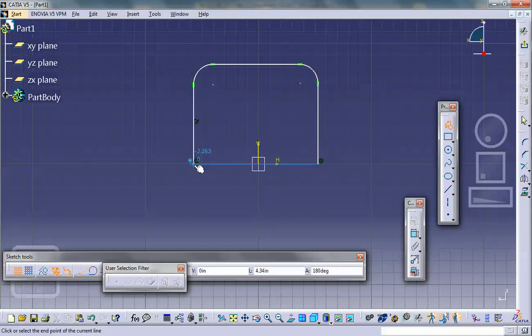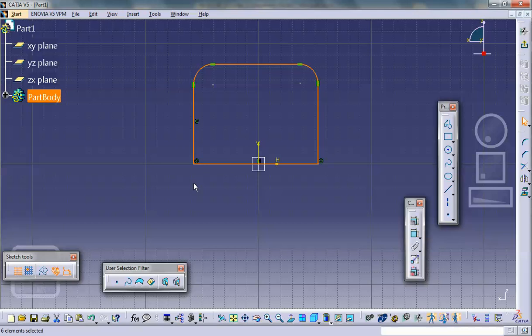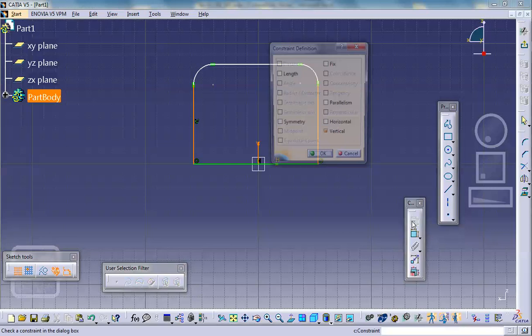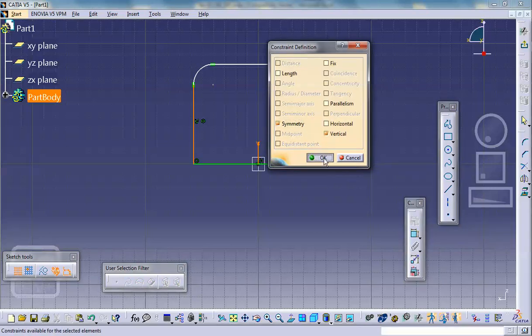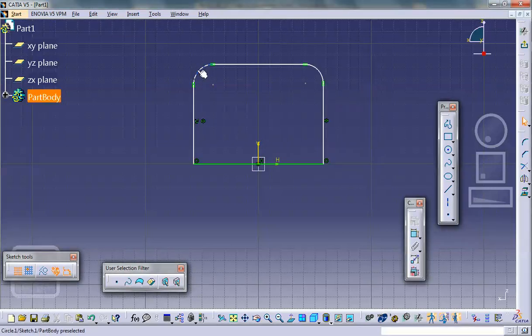And there we are. We have to do some cleanup here. Left side control, right side control, the middle axis. We make it symmetric. And let's make sure these radii are also the same value. I'm not going to worry about dimensions here. I think they are. If not, you just put a dimension here and make it the same value.